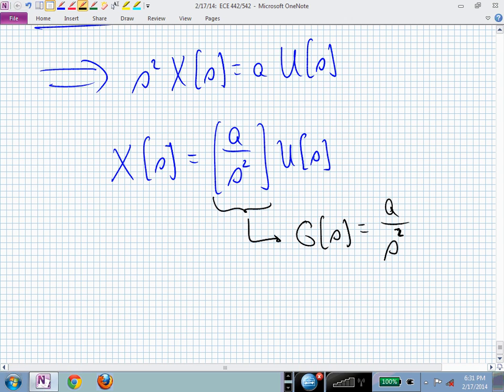Where are my poles of that system, pure mass system? I have two right at the origin. I have two poles at the origin. Where are my finite zeros? Finite values of s that cause G of s to go to 0. I don't have any finite zeros, do I? How many infinite zeros do I have? How many infinite values of s cause that to vanish? I could let s go to infinity this way or that way.